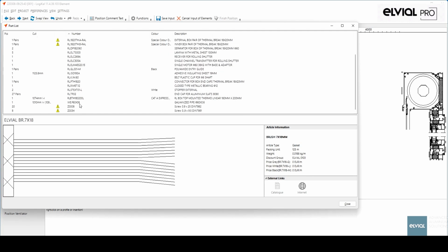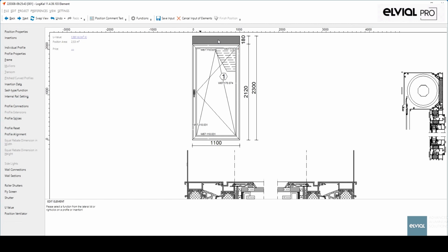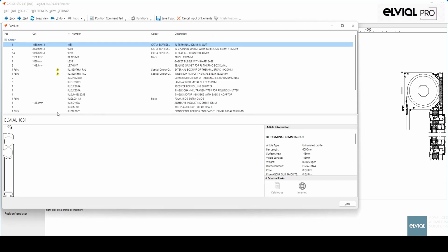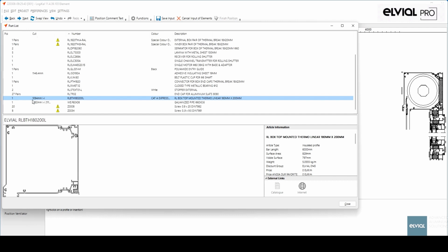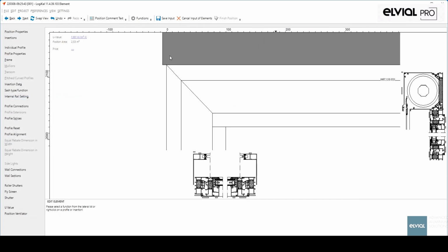As we can see in the piece list, the cutting length of our housing is 1074 mm, and it is affected by the gap that we inserted. For the record, the cutting dimension is width minus 16 mm. So let's change this gap and make our roller shutter bigger by 5 mm from each side. The width now is 1094 mm. That is 10 mm bigger than the one without any gap change. Of course, it's needless to say that all parts of the roller shutter are affected by this change.